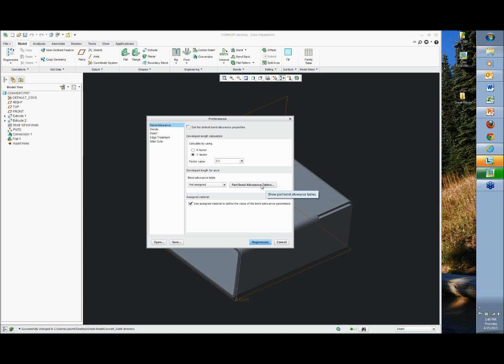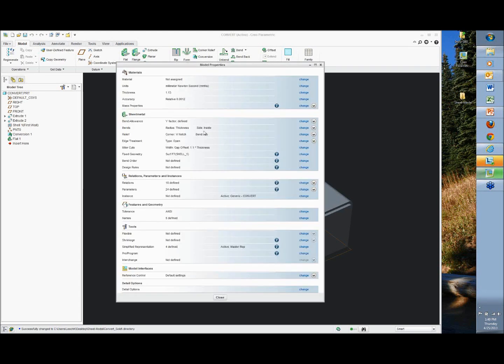And it might sound kind of picky, but if you're doing some detail type sheet metal where, say, 2 or 3 bends and you got some distance off an edge that you try to hold, and you're off on a bend deduction by 5 thousandths over 3 bends, it's 15, 20 thousandths. And again, maybe it's not a big deal for a lot of people, but for some companies, that's too much to be off. So these are where you're getting a little bit deeper and set that stuff up.